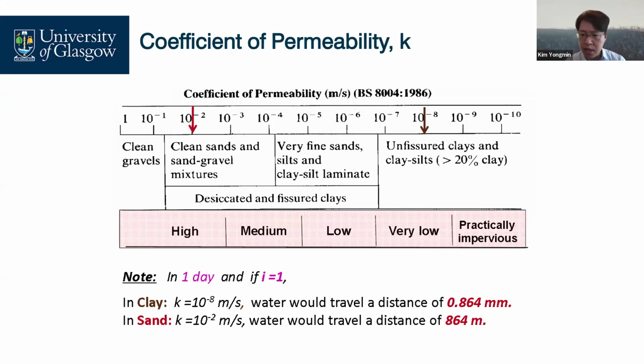In clay soils, the structures, right? The gibbsite, there is the stack, the shape. You remember, right? This structure plays an important role in permeability. And coarse material like sand and gravels have a relatively higher permeability. On the other hand, the fine materials like silt and clay have a low permeability compared to the coarse grain materials.